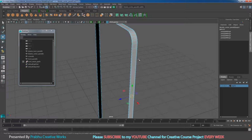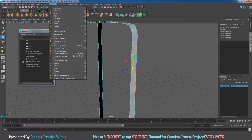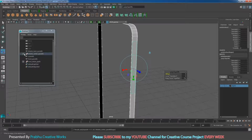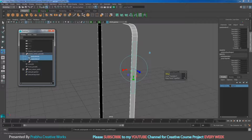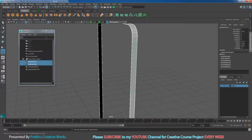Now right click on this face over here, go to edit mesh and choose extract. That means you have two objects over here. I will select these two objects and press Shift P on the keyboard, so that means it will leave the group. When the objects are selected, go to edit, delete by type and choose history. So our history will be gone.